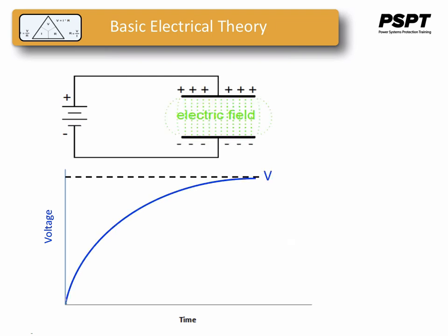If a source of voltage is suddenly applied to an uncharged capacitor, a sudden increase in voltage, the capacitor will draw current from that source, absorbing energy from it until the capacitor's voltage equals that of the source. Once the capacitor's voltage reaches this final charged state, its current decays to zero.